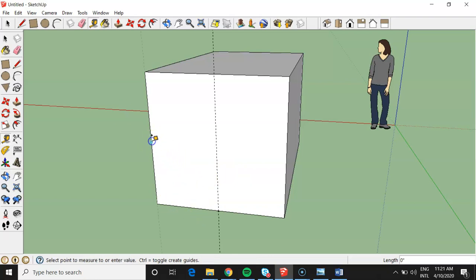Another is to just pull off of the edge. I'll show you. To create a window, I'll pull from this one. So I found the middle, and let's say my window is 2 feet wide. I'll click once with the left, pull over 12 inches, enter, and then do that one more time. Into the tape measure, click, pull over, punch in 12, enter. So that is finding my center and then moving to find my window parts.